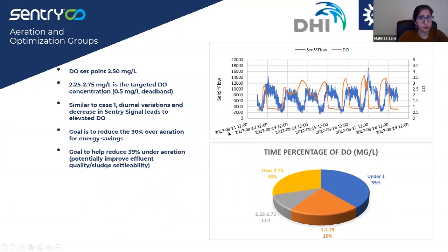The next step for this project is to try suggested aeration control logics on local plant SCADA with no control of the actual plant. And depending on the success of this step, in the third phase, we are going to implement the logic on 1 reactor or 1 train and monitor the results for a set time period.